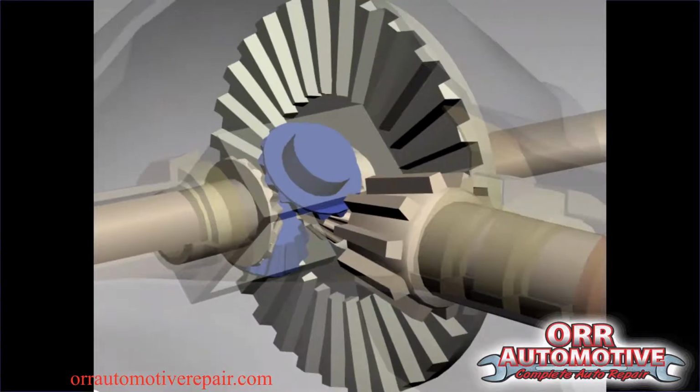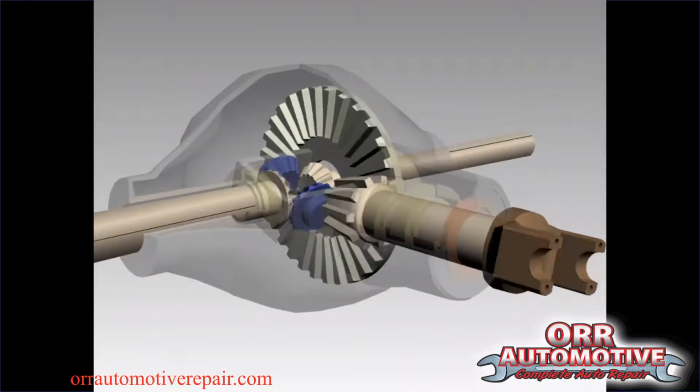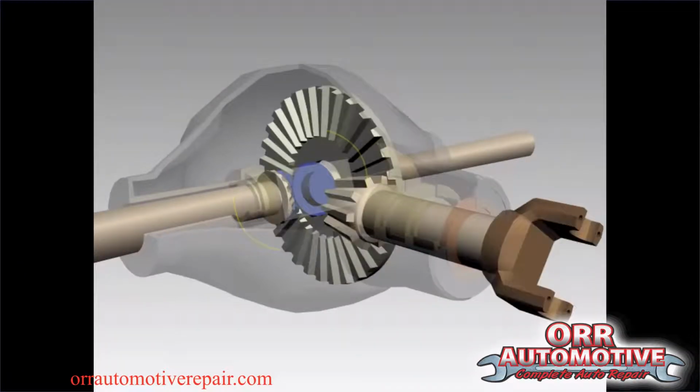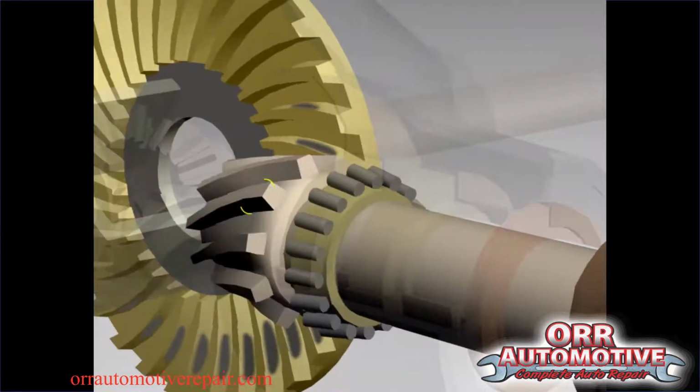When the spider gears become worn, the side gears and spider gears do not create a tight mesh and can skip over each other. This usually makes a loud popping noise when cornering.